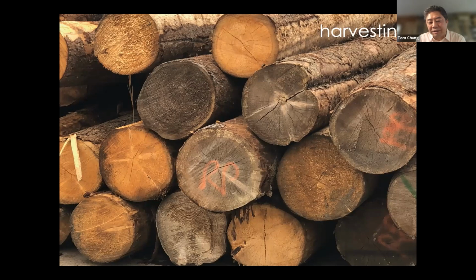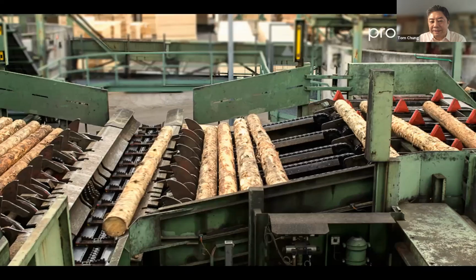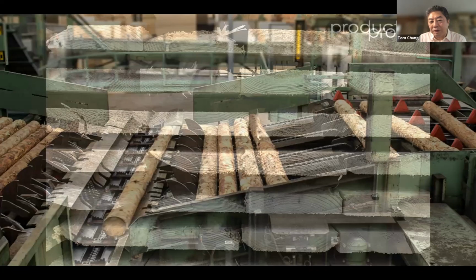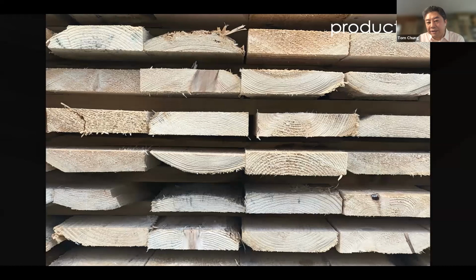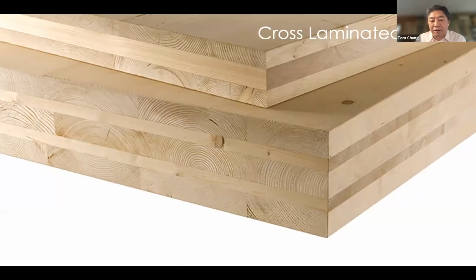First, you have to cut down and harvest the trees. Then you're basically simply debarking that. Then you're cutting that whole tree up into lumber, smaller pieces. And in the case of mass timber, let's say cross-laminated timber as an example, you're now gluing those lumber pieces back into a single solid massive panel that can really expand what wood can do in our construction.